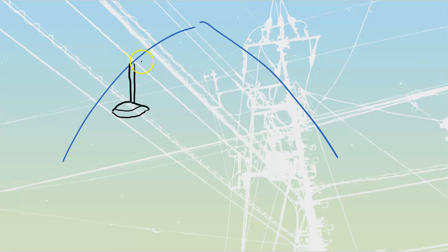What you're allowed to do is run your circuit conductors back to a remote mounted set of ballasts. Common places for this are architectural installations where they want to show it off as a feature. It's a fancy light inside of a fancy ceiling that they want people to ooh and ah over. The other place that we commonly see it is inside of gymnasiums. Gymnasiums are obviously rough on surfaces, with basketballs and stuff like that. They carry a phenomenal amount of weight, so if you have a ballast up there, there's a greater chance that if something comes down, it's going to come down hard and do some damage to people. It's also going to be easier to knock off the ceiling because of the amount of weight. So we'll mount those remote.